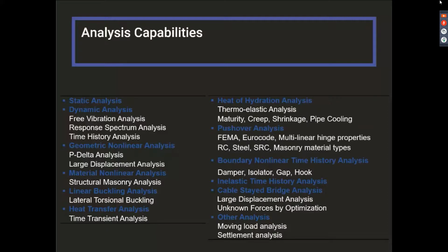Advanced analysis such as pushover analysis and boundary nonlinear time history analysis can also be performed in our software. Different databases of dampers, isolators, gaps, and hooks are available already. For cable stayed bridges, we have separate analysis known as large displacement analysis and the unknown load factor optimization.